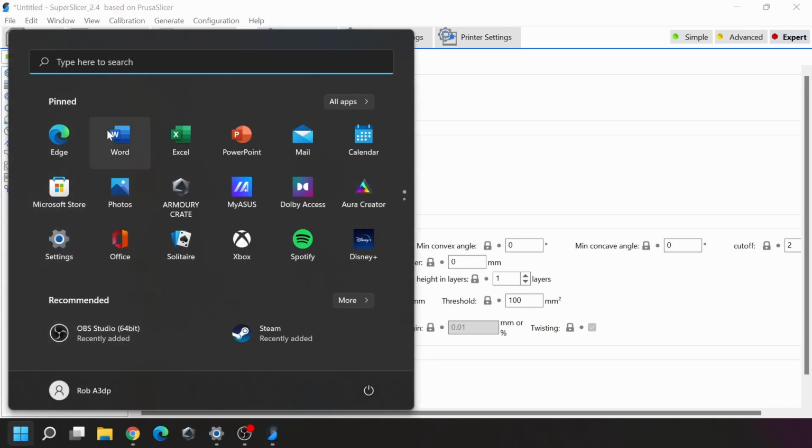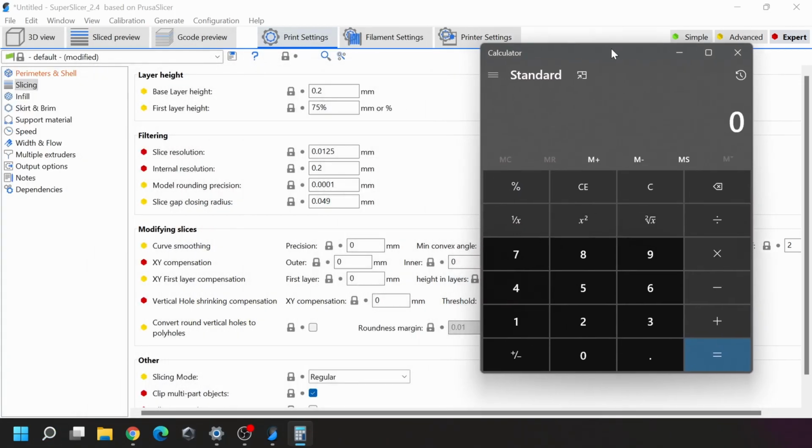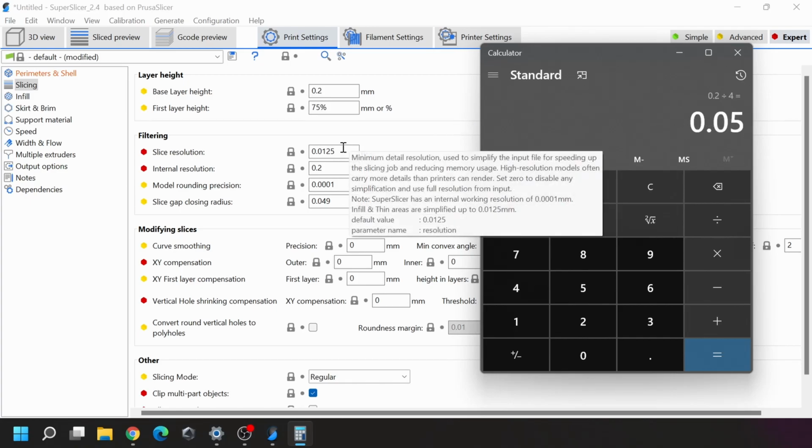So once again, let's open up a calculator. If you're using GT2 belt most likely, so it's 2 millimeters per tooth. And if you're using 20 tooth pulleys, basically that's 40 millimeters per rotation. So 40 divided by 200 if you're running 1.8 degree steppers is 0.2. We can expect quarter step accuracy again. So 0.05. So honestly, there's really no reason to go beyond 0.05.